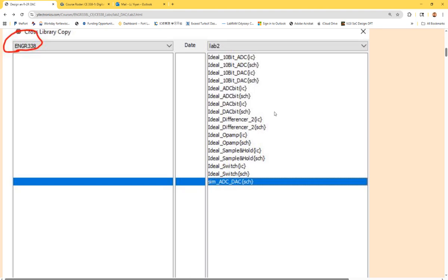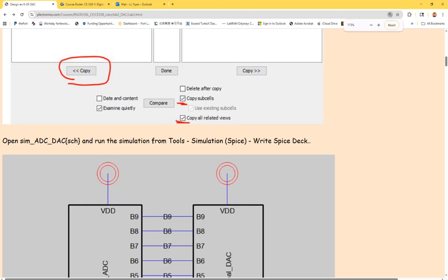It's a simulation file, not a chip, so we are not creating an icon from it. It doesn't make sense to create an icon because a simulation file usually has a voltage source in there, like a battery. When you are doing chip design, there's no battery, no power source in the chip. You just leave the ports and connections available for the voltage source. So this simulation file will be a singular file sitting in the library without any other files for that library. You'll see this in the next few figures.